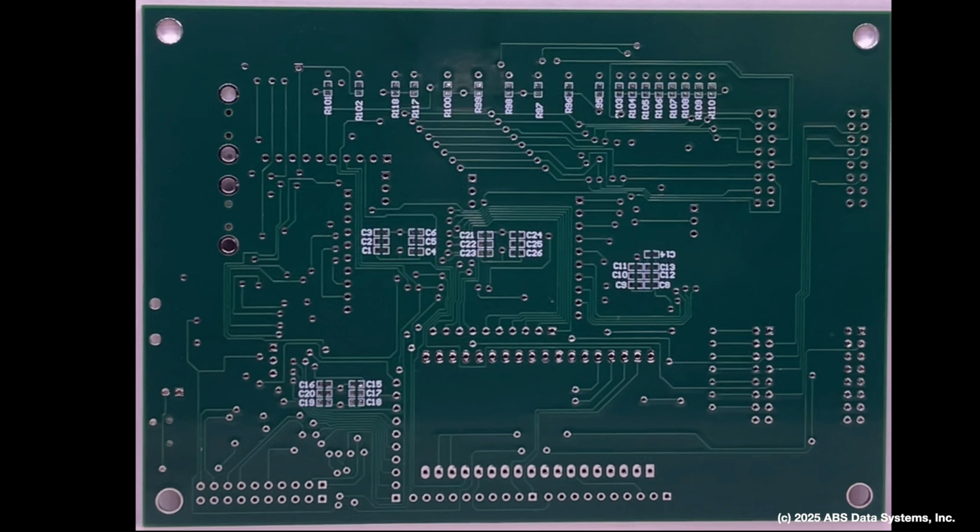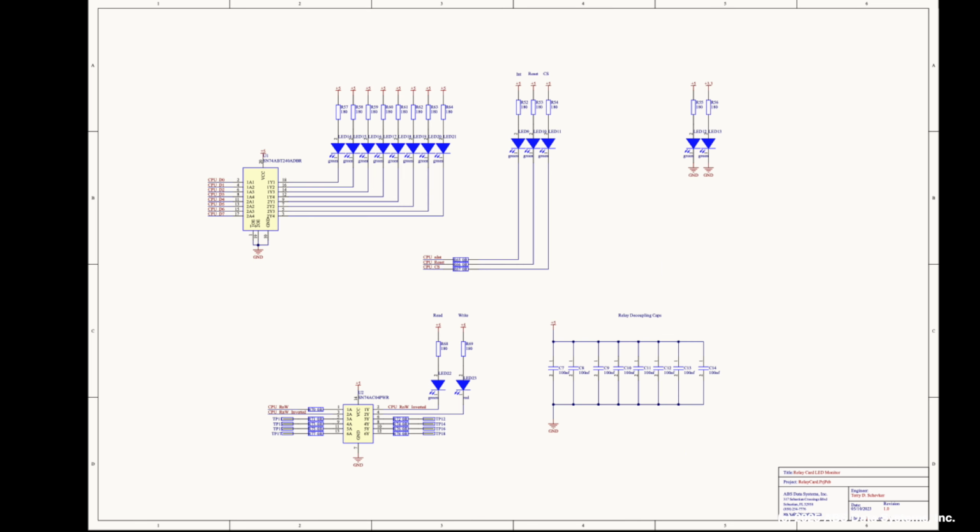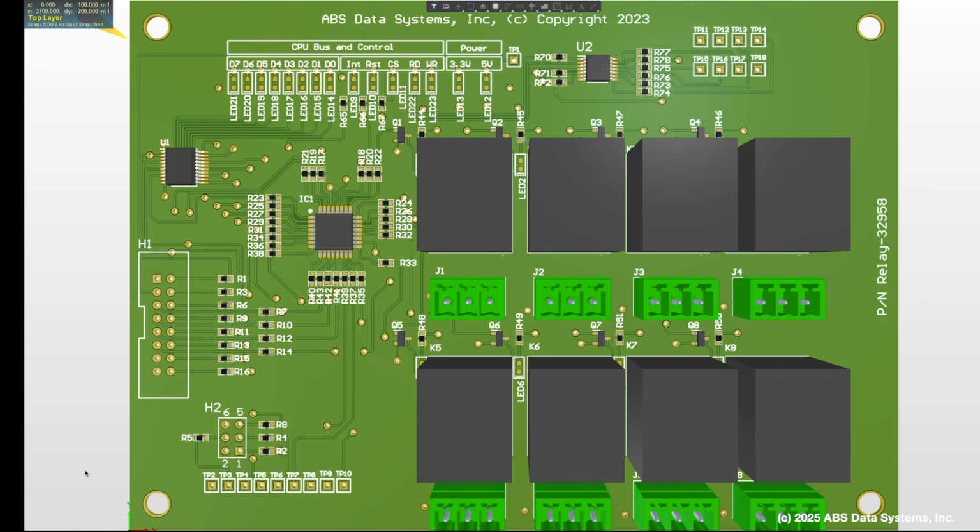My first step was to eliminate the need to remove the ROM. Then I thought, I need a serial port, maybe hardware for display, a keyboard, and well, that's how I ended up with my 6502 project. I've designed a series of boards, 14 in all. I added 12 slots to the CPU board for peripheral connections, plus a ton of extra memory and EEPROM space.